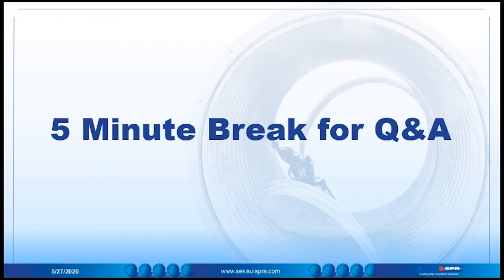Great, thank you, Chris. The next question is, how much reduction in hydraulic capacity can you expect using spiral wound liners? I can take that, Ryan. Due to the improved Manning's coefficient of 0.009, our Sekisui PVC liners can typically equate if not improve flow capacity post-rehabilitation. Our design calculations will include this information in the design summary to verify our liner design can meet specific hydraulic requirements.